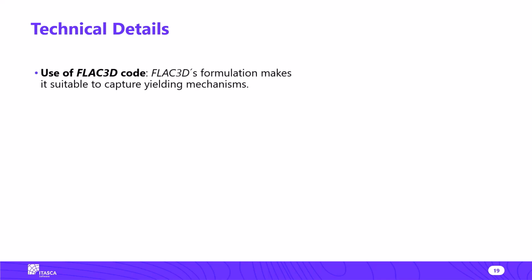On the tool selection, it was quite clear from the beginning that the analysis needed to take into account the plastic behavior of the rock mass, as the pillars were exhibiting relevant deformations. This led immediately to consider FLAC3D as the tool of choice, given its use of the mixed discretization technique. Then the question comes, what about the need to include geological structures? Isn't 3DEC better suited for that?